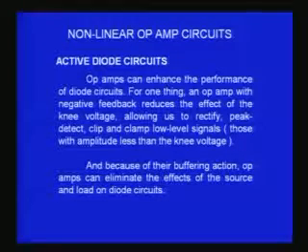If I say 0.7 volts in millivolts, it is 700 millivolts, which is a very large magnitude of voltage, and you will get only 0.3 volts if it is 1 volt peak, which is about 300 millivolts. So you have lost 700 millivolts of your input voltage across the diode. This is a very undesirable scheme. So how do I then detect very low level signals? How do I measure a very low level signal?